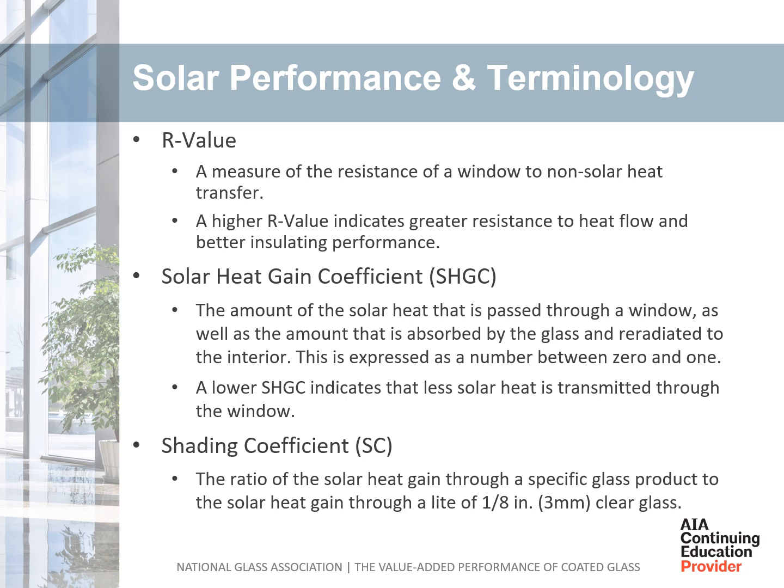Solar heat gain coefficient is the ratio of solar heat gain entering the space through the fenestration product to the incident solar radiation. Most simply put, it is a ratio that includes directly transmitted solar heat and re-radiated absorbed solar radiation.